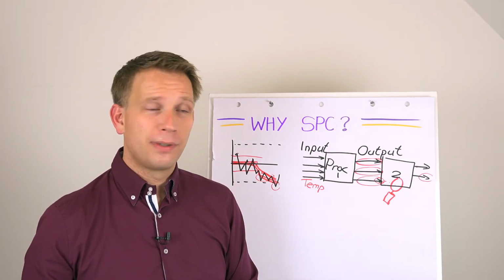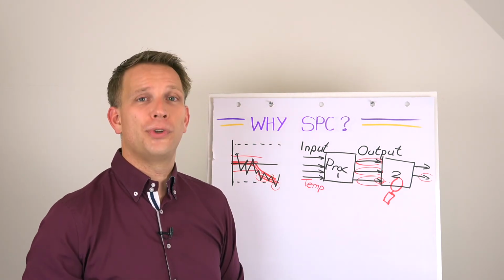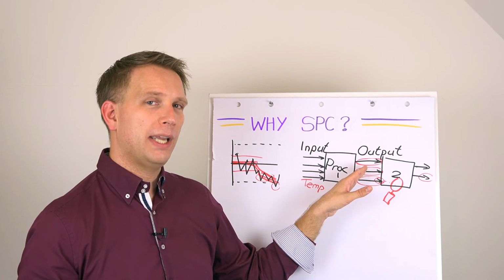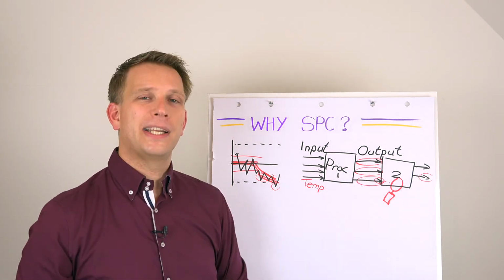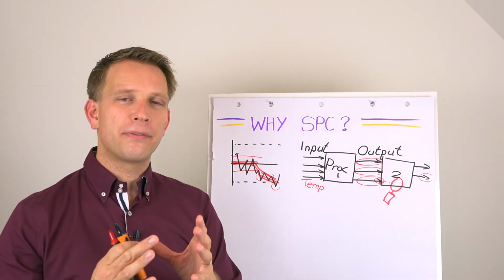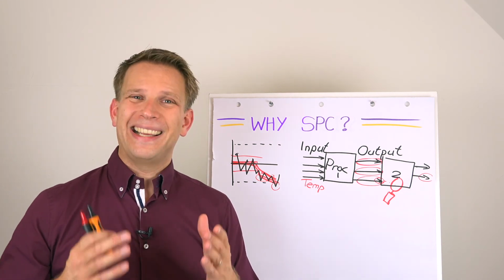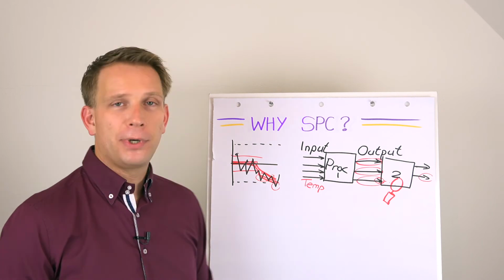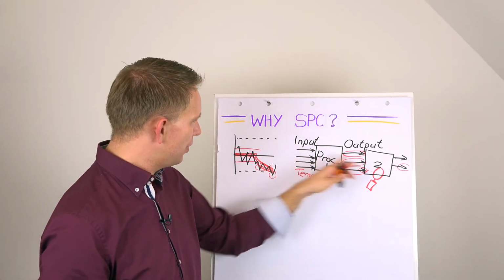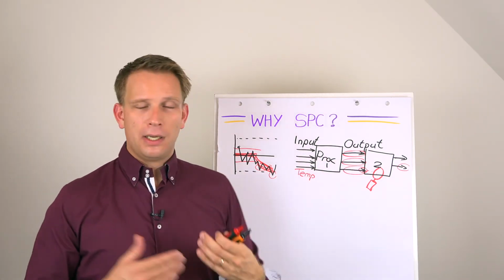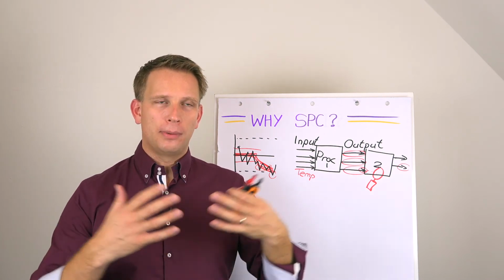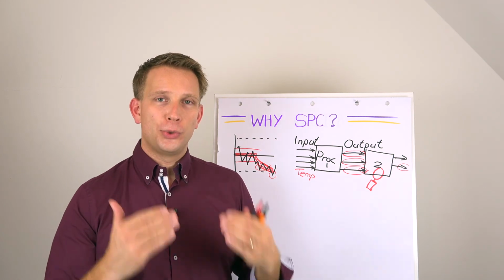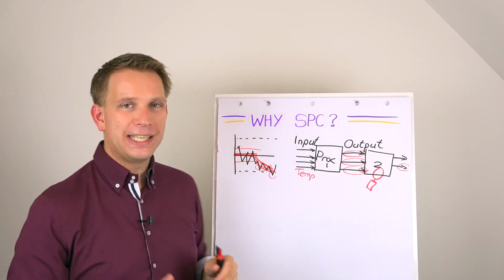So for those, you need to control the processes, not keep them roughly within specs that would be okay on the market, but try to keep it as close to whatever ideal norm, or in fact as close to itself as possible. That is a brilliant part to do SPC. So when we do SPC in our operation, it is to check if our process is deviating.